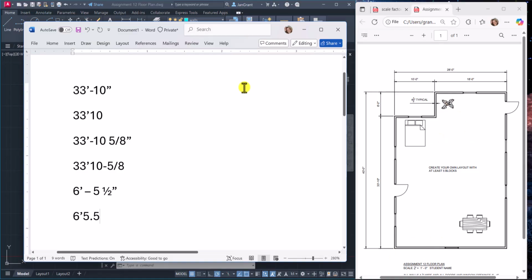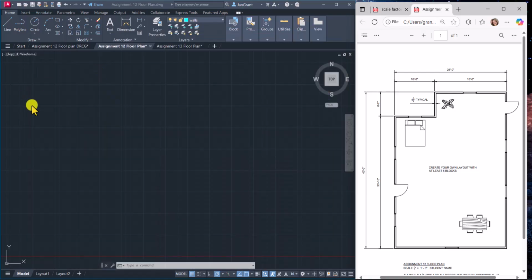Instead of using a line, we're going to use a polyline. And also, we are zoomed really far down, on a very small level in that really small corner there. So there are at least 3 or 4 different ways of zooming up to our workspace. Some people use limits. I prefer to just draw a line that's 28 feet and then zoom back out to that workspace.